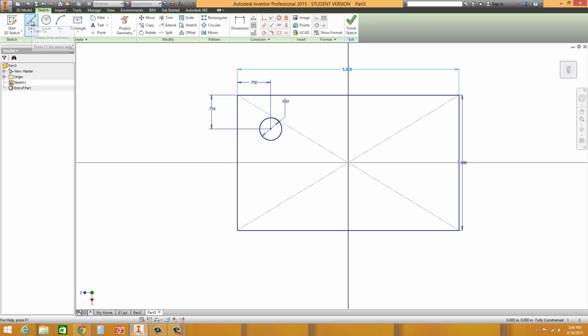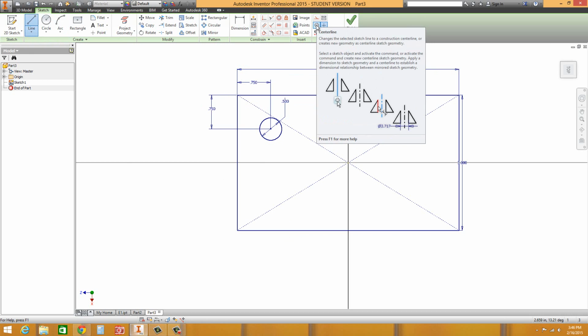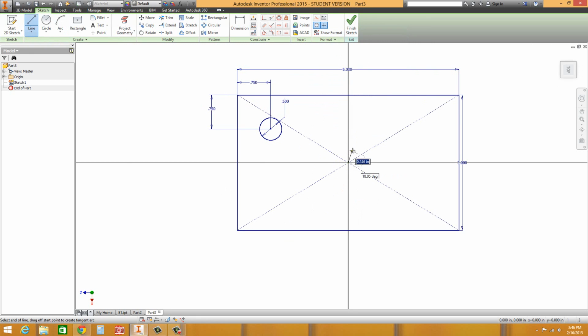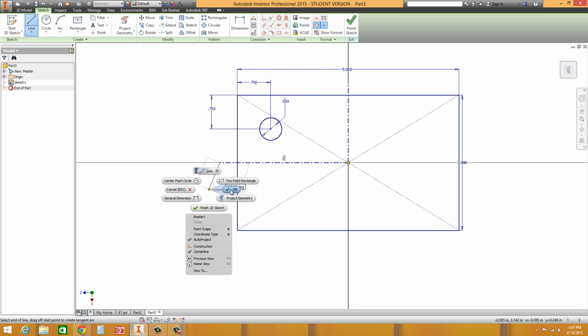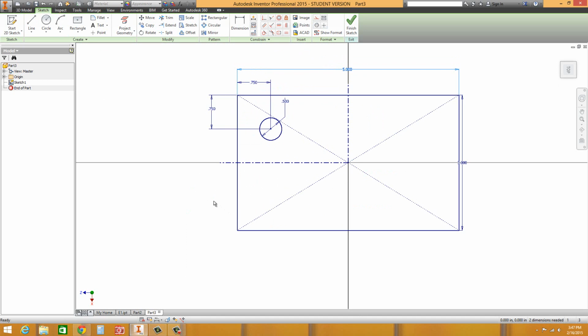I'm going to go to the line tool here, and over here, when you want to create a center line, click on center line. There's also construction lines. They both do the same thing in this case. Click on center line, and let's draw a vertical center line from the center, just straight up like that, and then hit escape. Click on line again. Click on that center point, drag out a nice center line here. Be aware you could always right click too, and you can hit OK there, and it will exit you out. Also, there's end chain too. But anyway, the reason I drew the 2 center lines is because that's the primary ingredient needed to mirror anything over. Now you can't mirror on both sides at one time, so just be aware of that too.